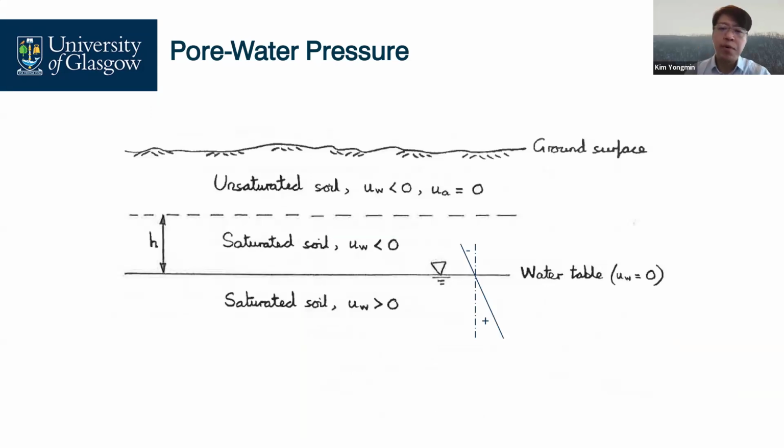So in general, below the water table, the water pressure is positive, with the value based on the hydrostatic conditions mentioned before. Above the groundwater table, the water pressure is negative, which is also under hydrostatic conditions. Negative water pressure, we sometimes call it matric suction. It is kind of suction. When you suck some water through your straw, that is negative pressure, which attracts the soil particles together.